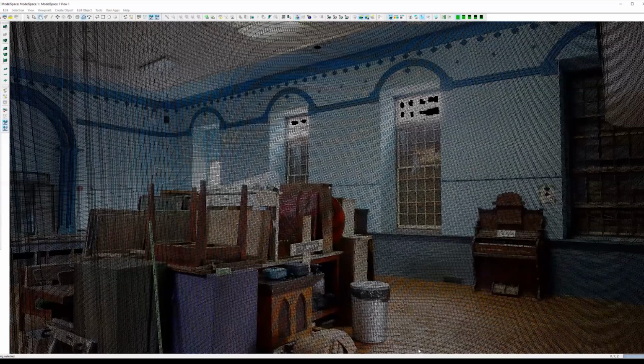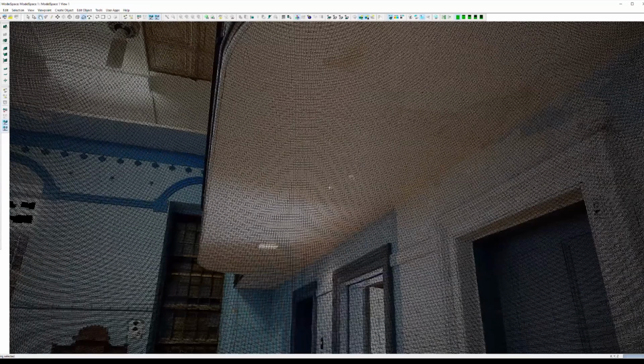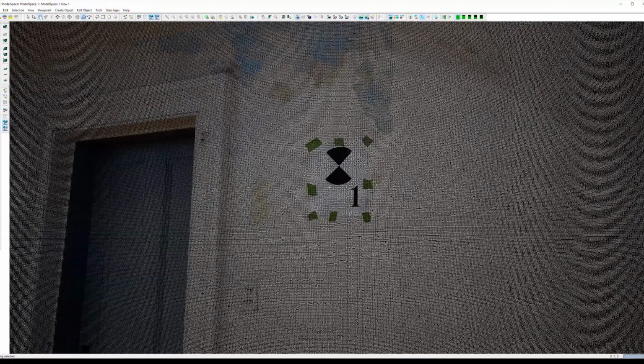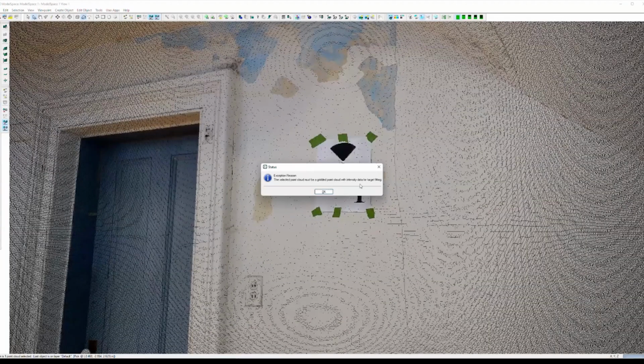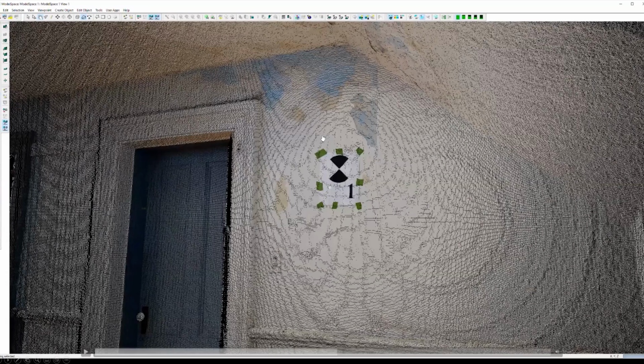And then we switched to the point cloud. So it is sparse. It records 100,000 points per second, so I think each scan was about 5 million points. But the thing that we noticed, when we tried to extract this target, we get this exception: we don't have intensity data. So I'm going to pause it here for a second. In order to extract these checkerboard targets, black and white targets, to tie it to control or to use these as spatial constraints, you need that.